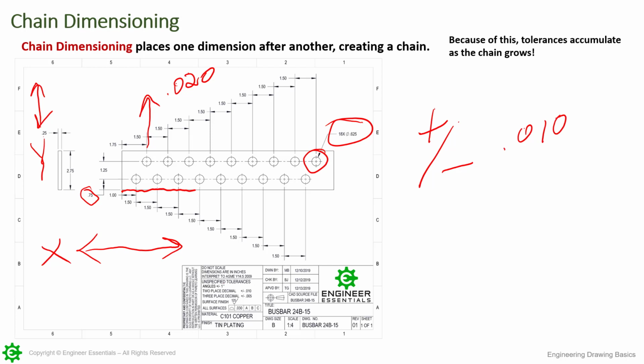So look at how far that can be off. Well, that 20 thousandths up, 20 thousandths down, now we have to account for that. So as far as what we can clear, we would subtract it out of here. So now looking in the up condition, we would be down to 600 thousandths that we could potentially clear there for this location. And of course, going down, we had the same situation. This could all shift downward as well. It could go down 20.